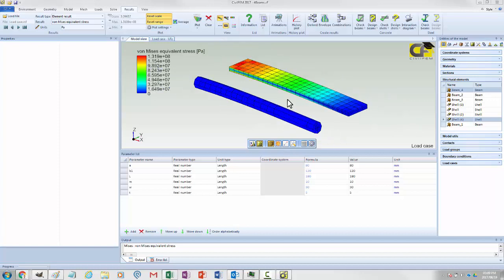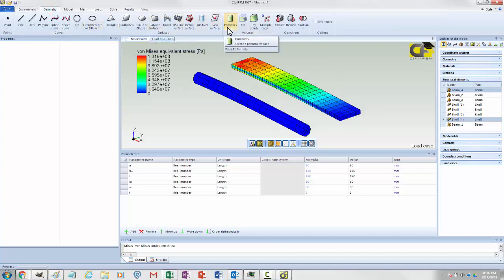We will now continue and create two additional representations of the same beam, but using solid elements. In this case, I could generate the solids using my primitives option, where I would need to recreate those solids using my parameters, or I could use the extrude option where I simply provide it with those original shell elements. So it would be better if I simply copy and translate the already existing shells or surfaces and use them in conjunction with the extrude option.